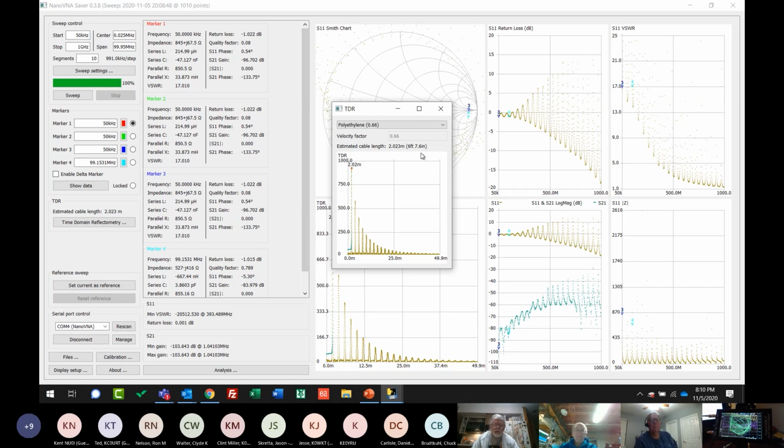Maybe your feed line's buried, and somewhere underground you've got a fault in your line. You could use this TDR capacity and get an idea of where you need to dig, measure back and approximate so that you can start looking at that particular point without maybe having to replace the entire feed line.